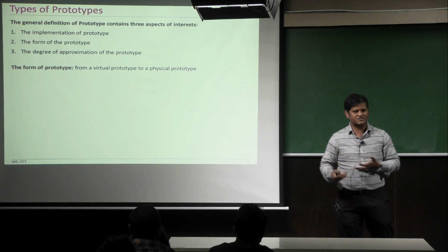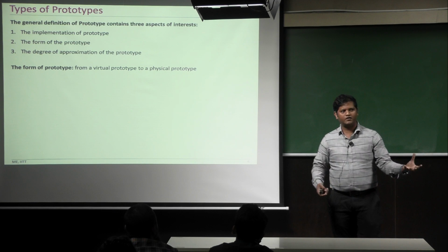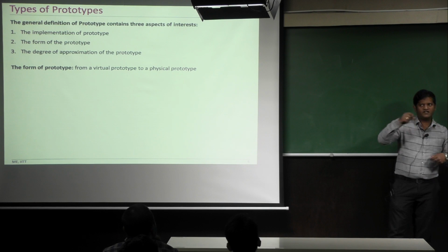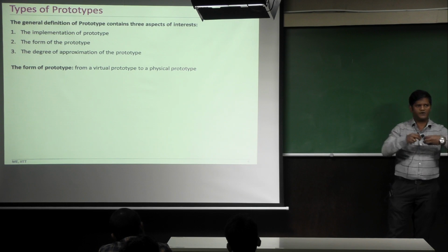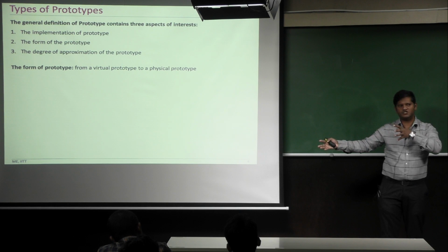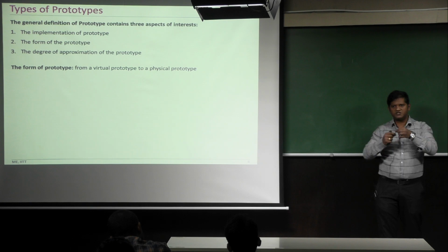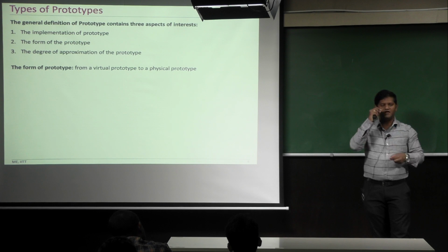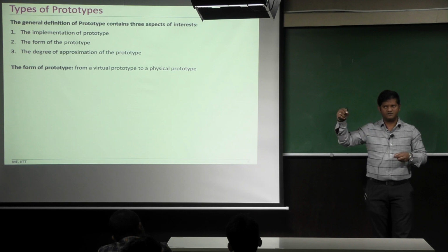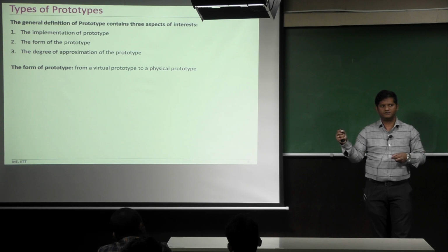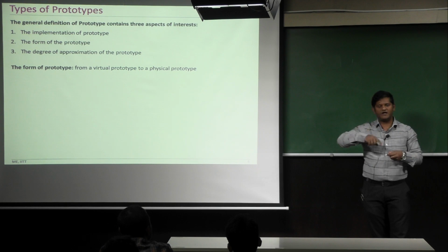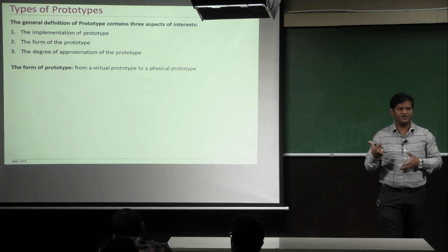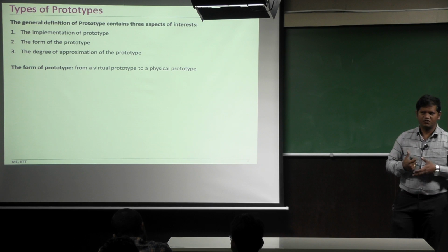Virtual prototype is the digital representation. In other words, you go for numerical modeling of the chassis development, and then you simulate the welding operation at multiple assemblies. At the end you estimate the distortion. If there is a distortion, then you change the sequence once again systematically, and you end up with an optimum welding sequence which gives the minimum distortion. All this testing can be done virtually in the numerical model, which is a virtual prototype, a virtual representation of the physical model and its functionality.